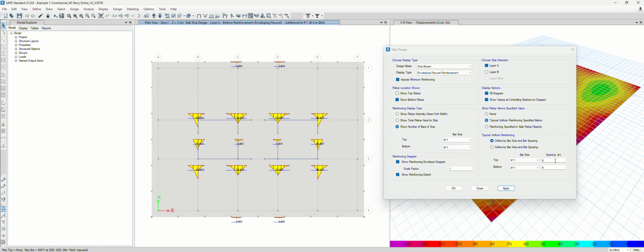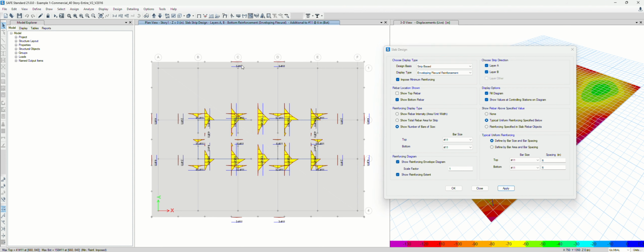So engineering judgment is something we need to bring, with our constructability understanding, so we can find a more reasonable or appropriate layout of the bar. So here I show you the bottom bar, but you can turn on both X and Y, but visually it's quite hard, so I just turn on and off.